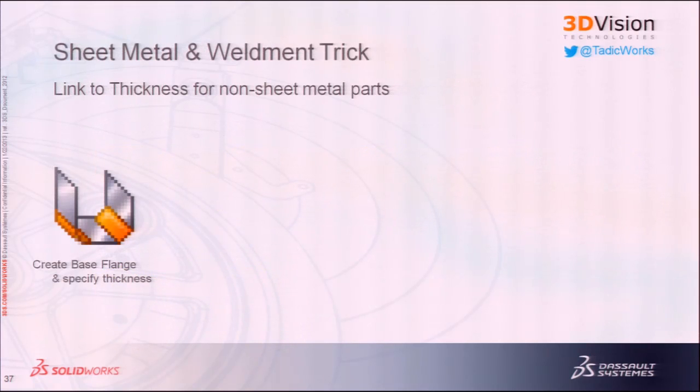Okay? So now we're going to get into modeling some things. This is one of my favorite little tricks, and that is for creating an assembly. Say you're making something out of panels, plate design as well, and you want to continually reference a uniform thickness. The example that we're going to use is we're going to make a cabinet out of 3/4 of an inch thick stock material.